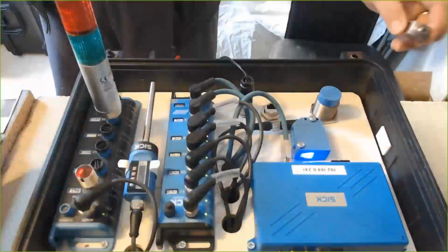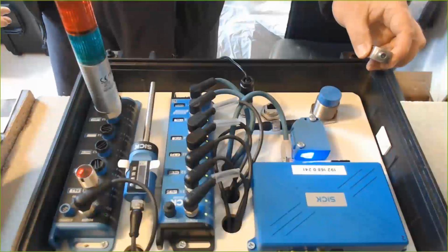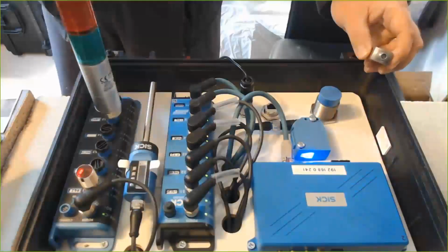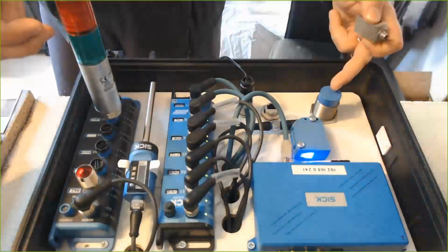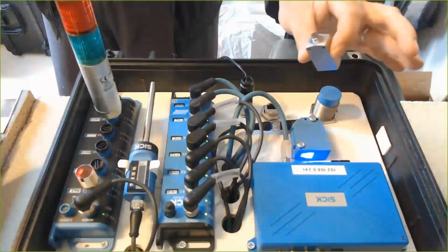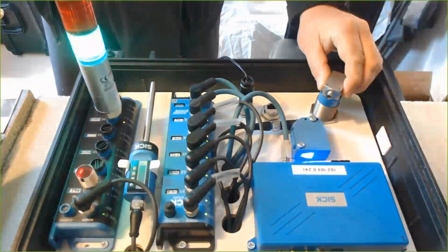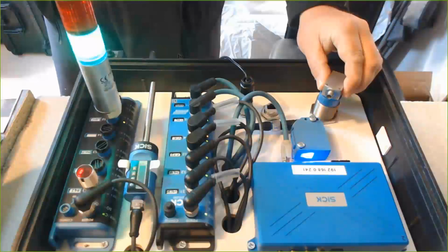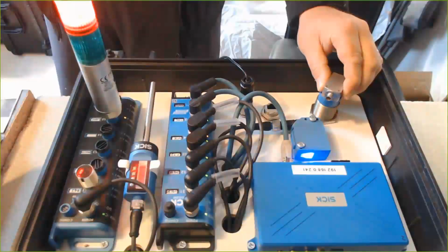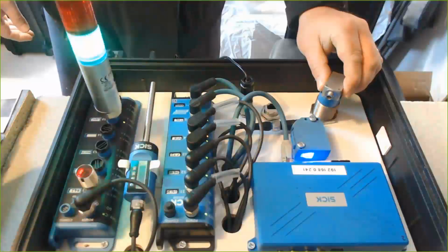So within the case, there's various components we've talked about. We've got the IMC in the top right on this shot, and you'll be able to see in a second that we're going to demonstrate a chain drift situation. So I've got a metal target, and I'm going to offer that up to the IMC and put it in what position would be deemed to be normal. So the chain is in an acceptable position, and we get a green output light. Now, if the chain were to drift, such as shown here by changing the position of the metal in the detection field, then we would get a red output light. And immediately we've got a localized solution for chain monitoring.